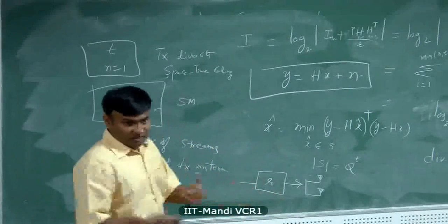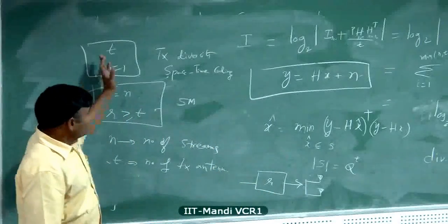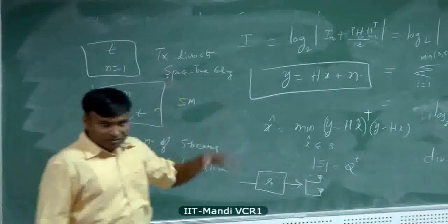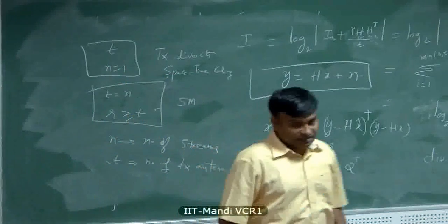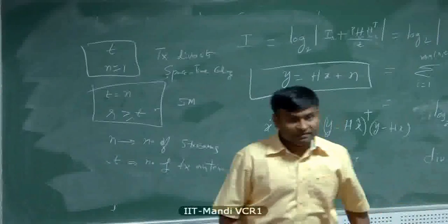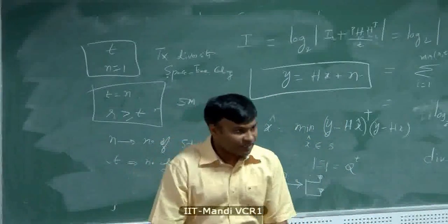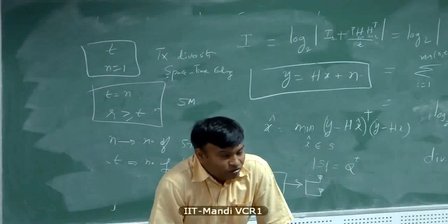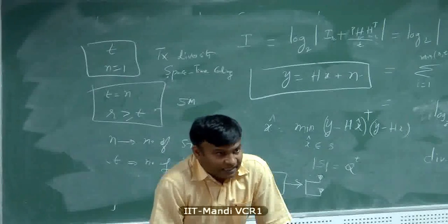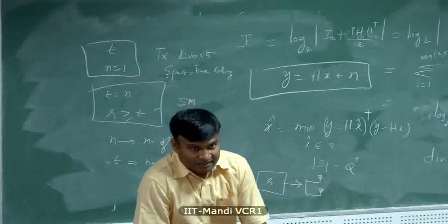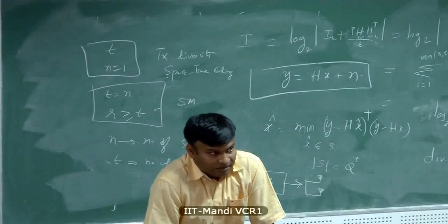And you can choose the configurations. I will leave it up to you: 2 by 2, 4 by 4, 2 by 4. Just take some numbers, a maximum of 4 antennas at the transmit and receive ends. Then there are some combinations. For spatial multiplexing, you need to do bit error rate simulation as well as capacity calculation. The rest are all capacity calculations. Okay?